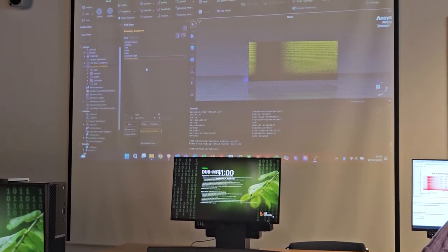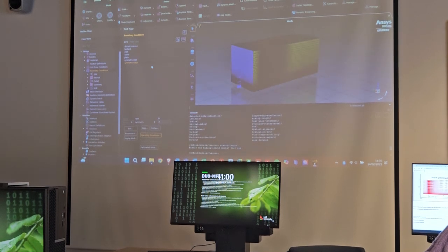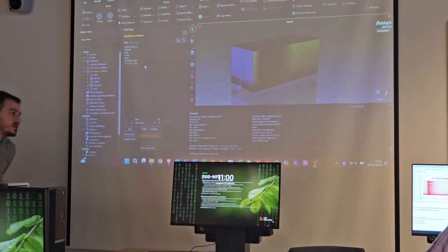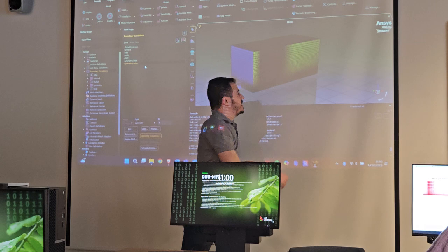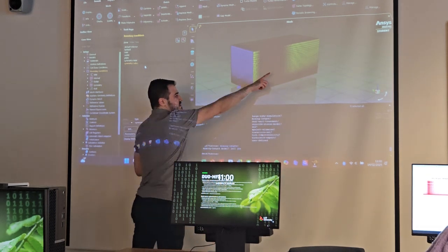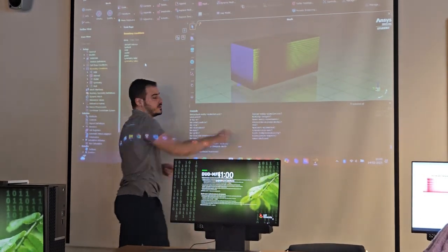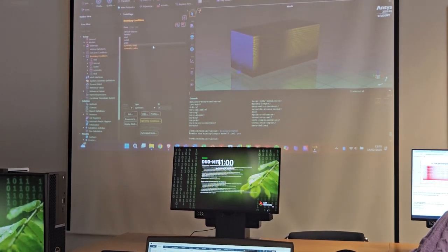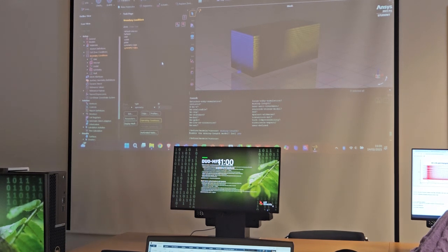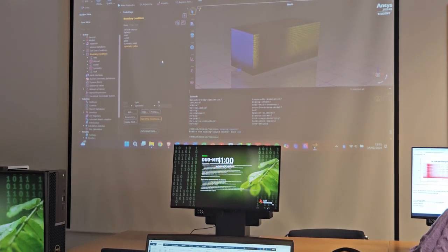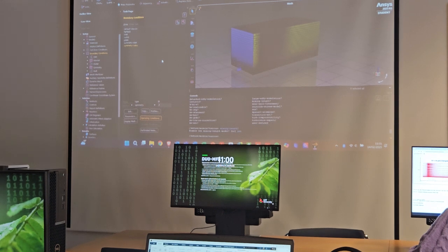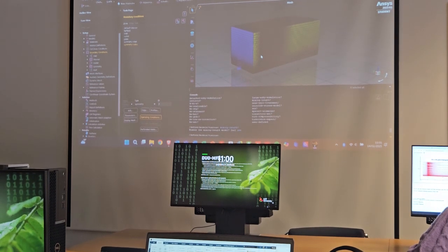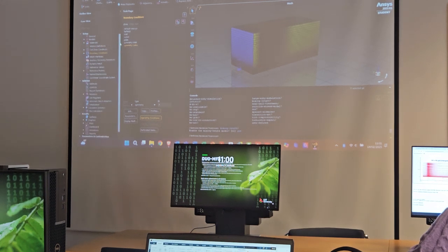Finally, we have the symmetry sides. In the 2D case, of course, you don't see this, so we have only one domain. But in the 3D, we need to set this surface and the parallel one. And we set them like symmetries, so that there are no real forces exerted on the flow, and the fluid is just flowing in that direction, parallel to the plate. So we don't change that.